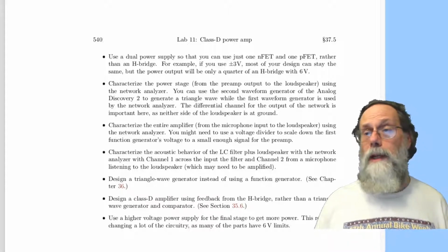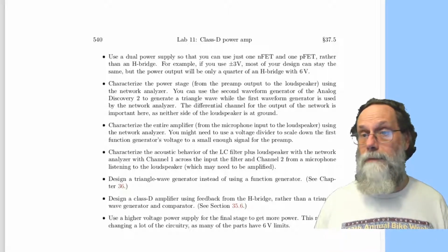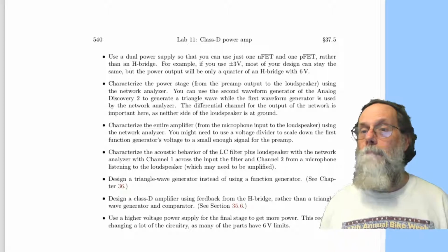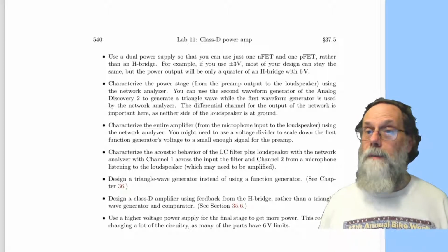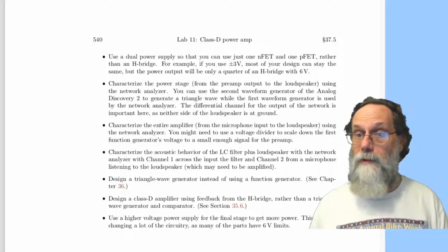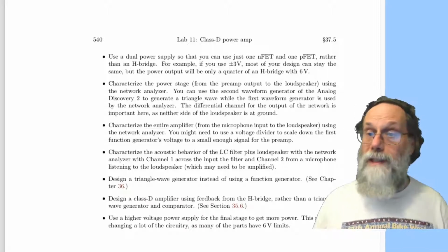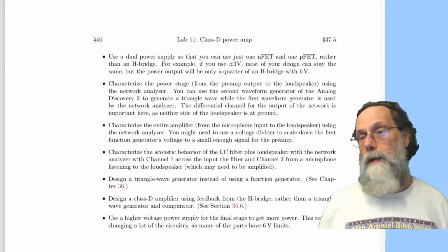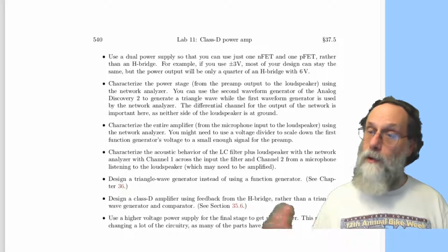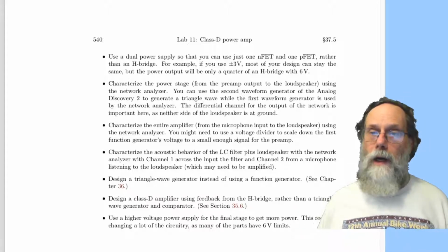You can use the network analyzer to characterize your amplifier, either just the power stage or the entire amplifier from the microphone input all the way to the loudspeaker. You can characterize the acoustic behavior of the LC filter plus loudspeaker by using the network analyzer, using a microphone to listen to the output of the loudspeaker. So you're looking at not just the electrical behavior now, but the acoustic behavior, what's happening out in the air.